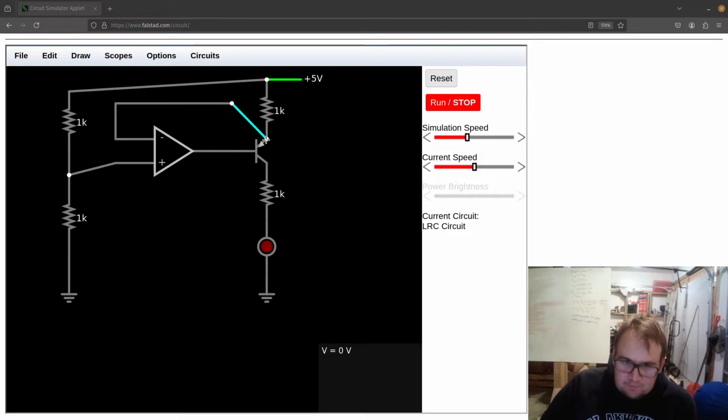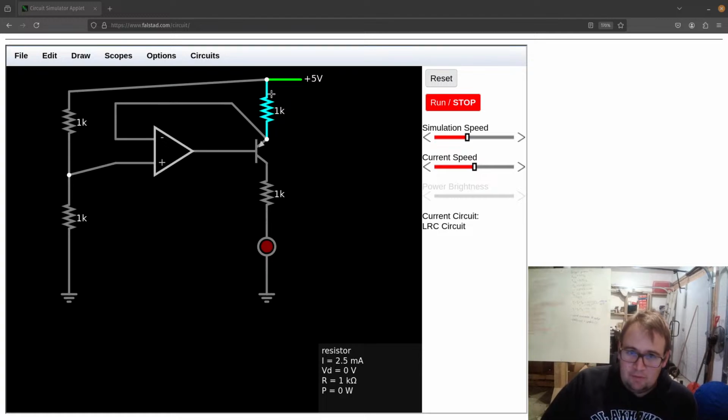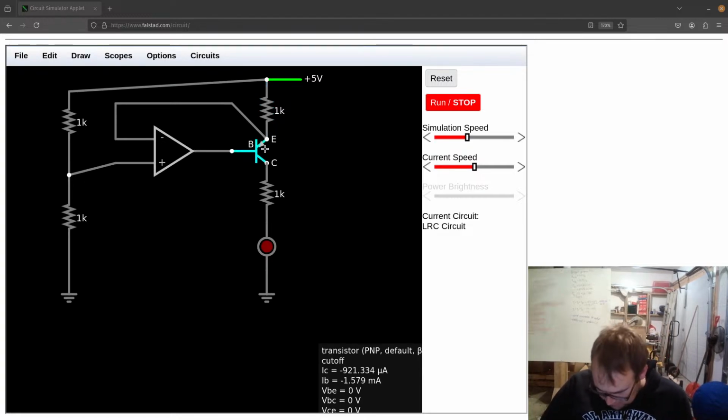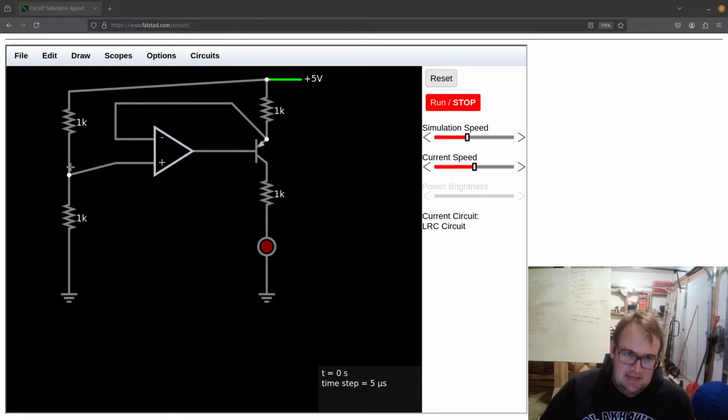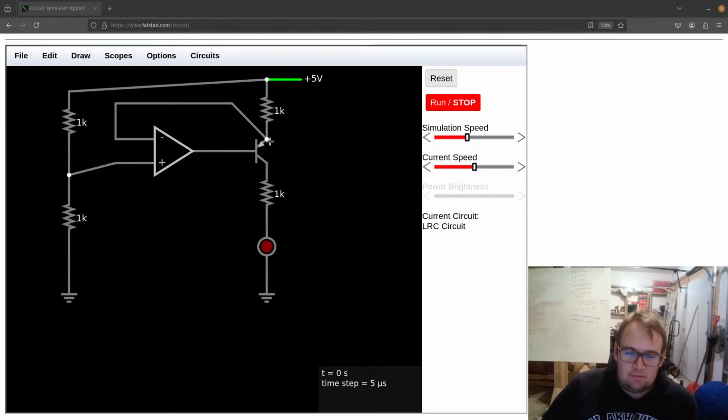drop this amount of voltage, like from 5 volts, whatever's dropped across here, and then the current going through will be that. So like that is VCC minus VN. So that's this one here. And then the current will go just from our V equals IR. So it will be 2.5 volts divided by 1K, 2.5 milliamps going down here.